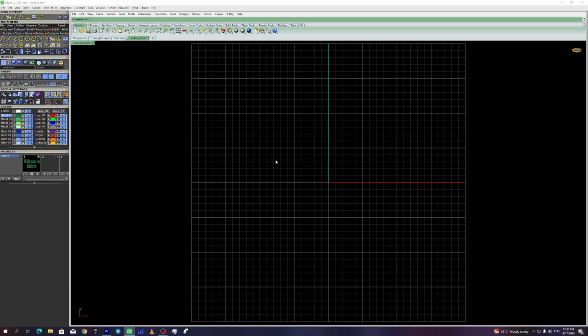The next command we are going to learn is explode. Let me explain it with a simple example. Imagine we have a rectangle, a polyline, and a circle on our screen. If we select the rectangle and run the explode command, something interesting happens. The four sides of the rectangle separate from each other. Instead of being one closed shape, they become four independent lines. The same thing applies to a polyline. It breaks down into its individual segments.